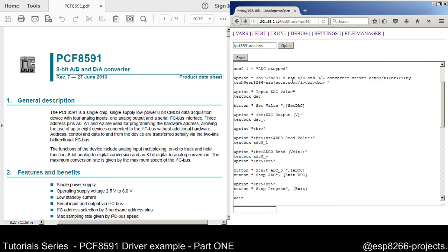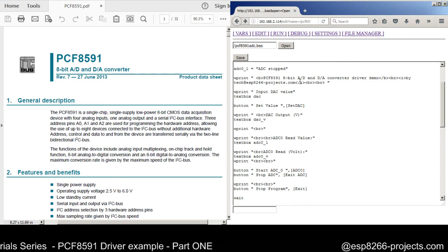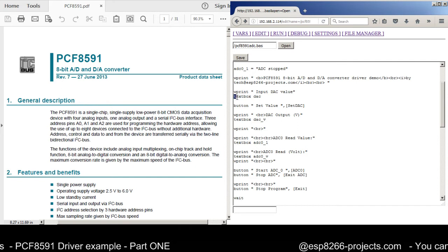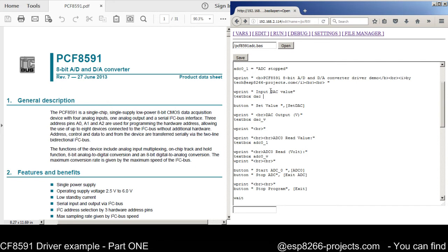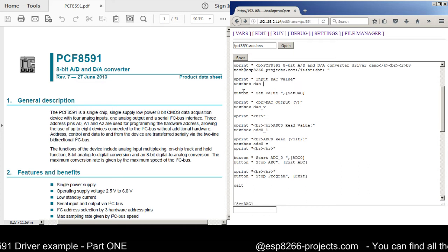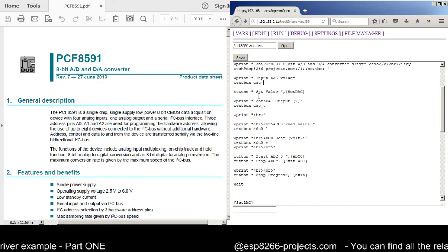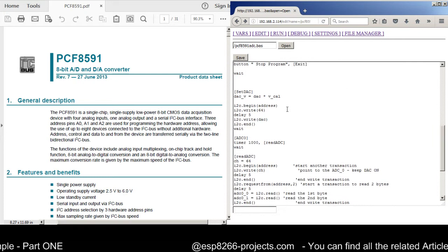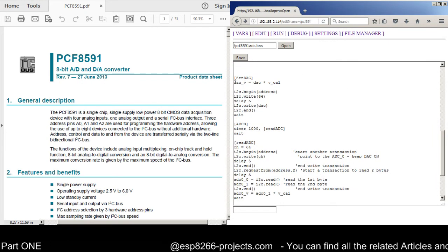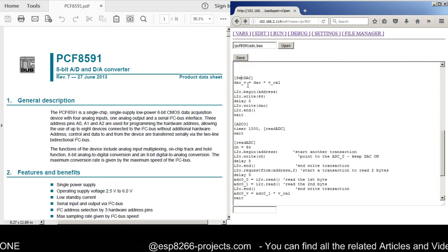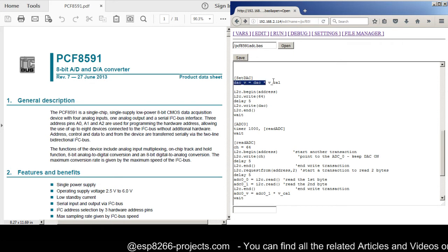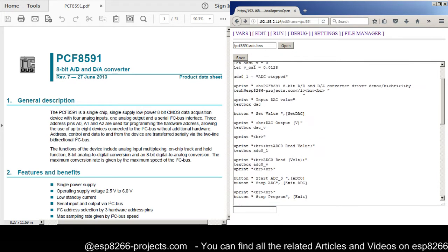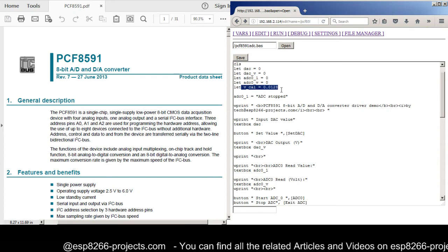In terms of the DAC input, it's the same thing as last time. So basically I have a text box where you can input the DAC value and the button that you will press, and when you press the set value button for DAC, it will jump in the set DAC subroutine, where the DAC value will be updated as the DAC value multiplied with the voltage calibration.